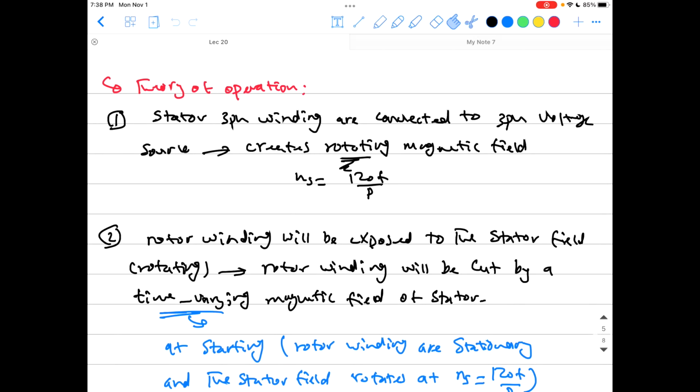Each member of them has to have its own component of magnetic flux, because the torque we develop in the machine is of the kind of excitation torque. Because the rotor of this machine is cylindrical, non-salient, you don't have any saliency torque. So we need excitation torque that needs two components of flux, one coming from the stator and the other one coming from the rotor.